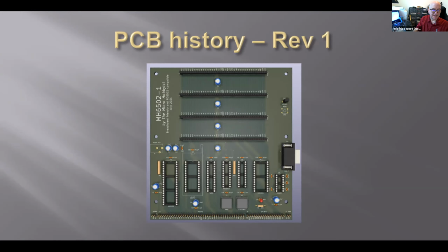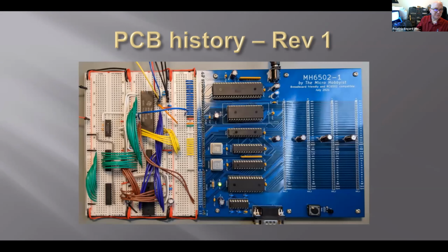And the slots that you see up there are the, what was it, RC6502 compatible bus, which I never really used because I had to buy or create new bus cards, which I did not want to spend time on. And at the bottom row is the breadboard connection, which I actually could connect a breadboard directly on. So this is what it looks like, all assembled and connected to a breadboard with the VDP on it.